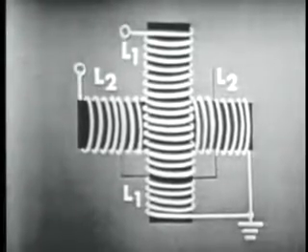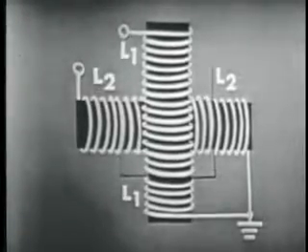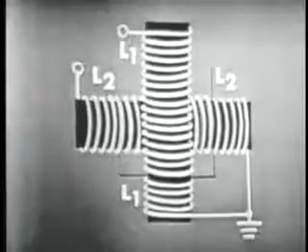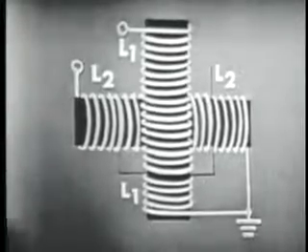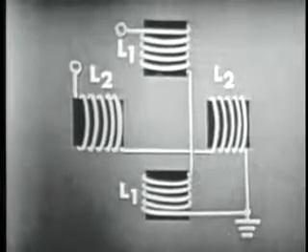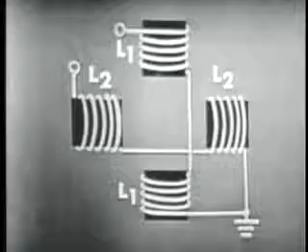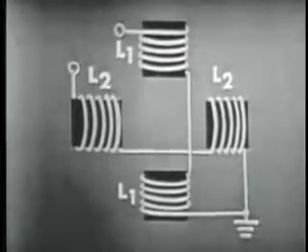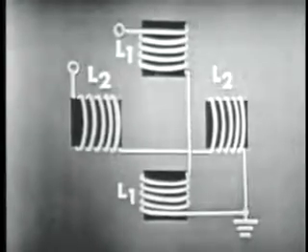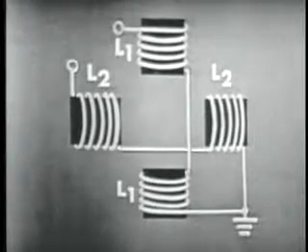Now, actually, there are really only two coils. We'll call them L1 and L2. Now, L1 was wound something like you see it, and then the core was cut in the middle and stretched apart. Now, it's still one coil, but now it's got a gap in the middle. L2, the other coil, was constructed in the same way. Now, L2 will supply a horizontal magnetic field, and L1 will supply a vertical magnetic field.